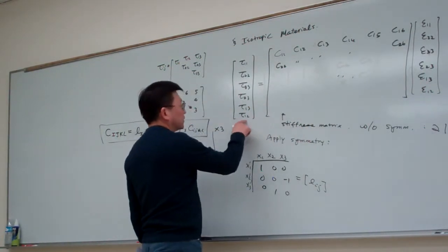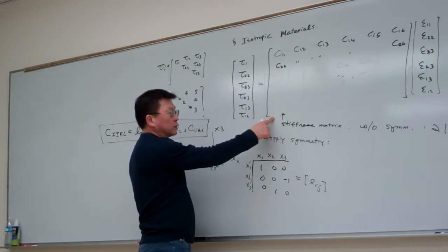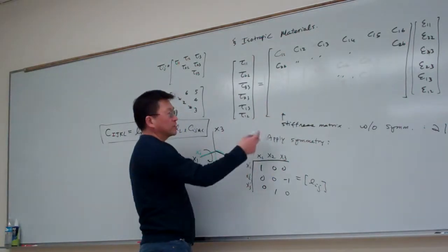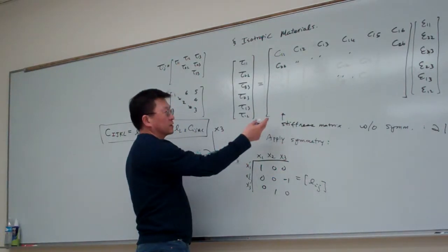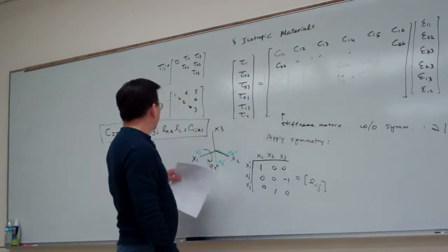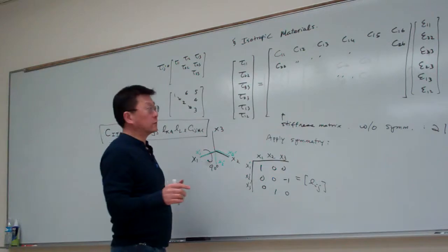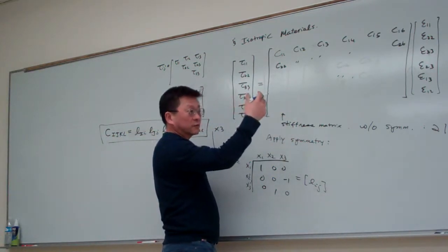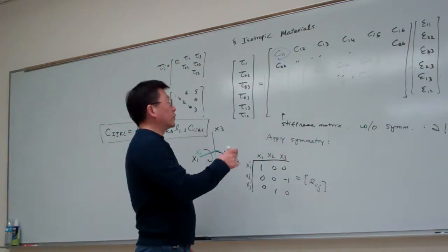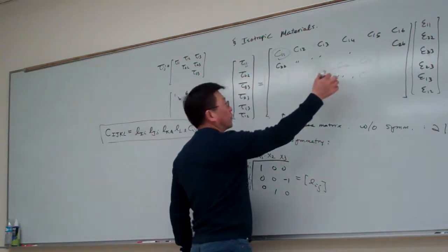Again, this is the ad hoc arrangement of fourth order tensors in a matrix form. It is convenient, but it distracts from all the beauty of the math. To utilize this equation, you have to convert this back to its very original. So if you remember, C11 relates to C1111, the primitive notation.